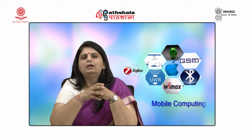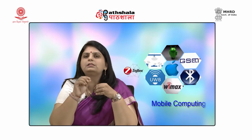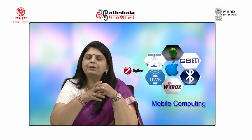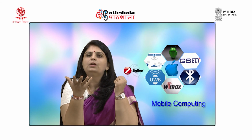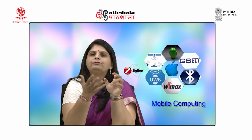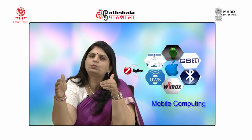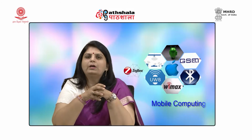Why does it happen? It happens because the distance has increased, and I just said that the received power is inversely proportional to the square of distance. So, as you move away, and this is for the isotropic antenna, the signal radiates from the transmitter and spreads along the area of a sphere. So, if I go away from the transmitter, the area increases as the square of the distance, so the strength of the signal reduces as per the square of the distance.